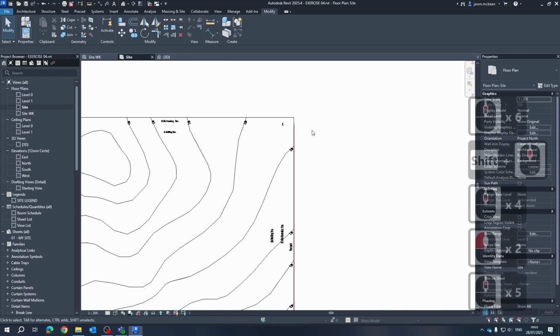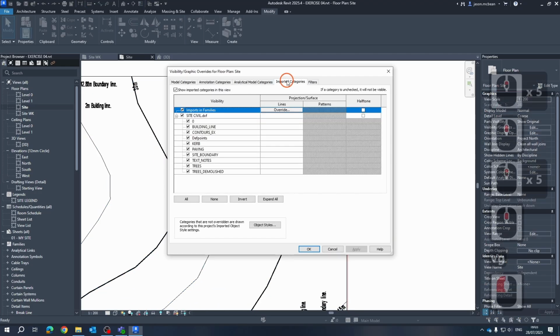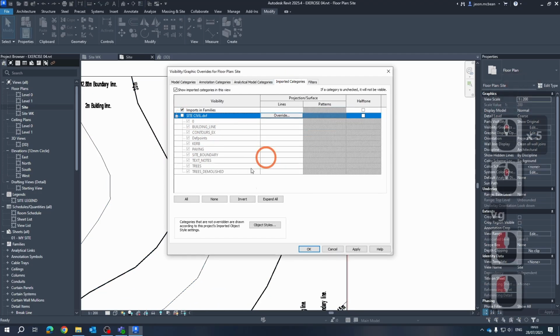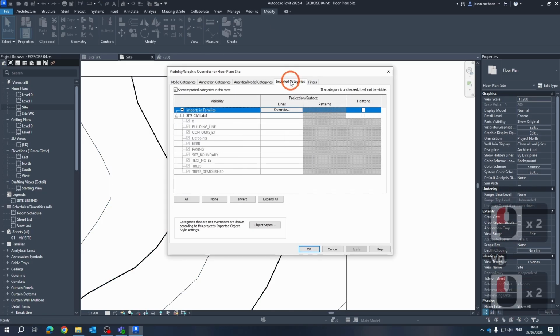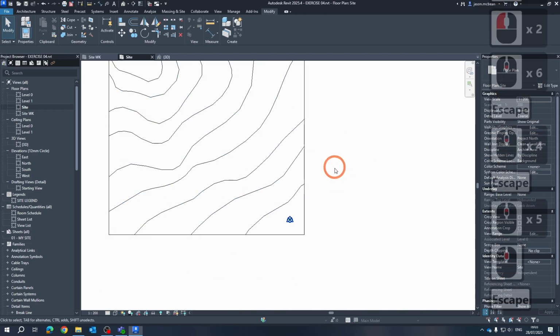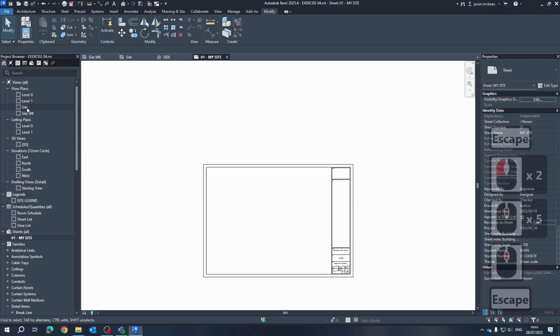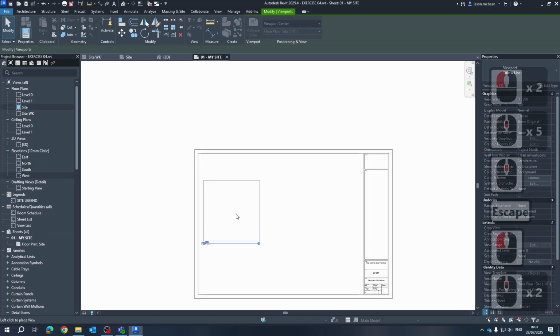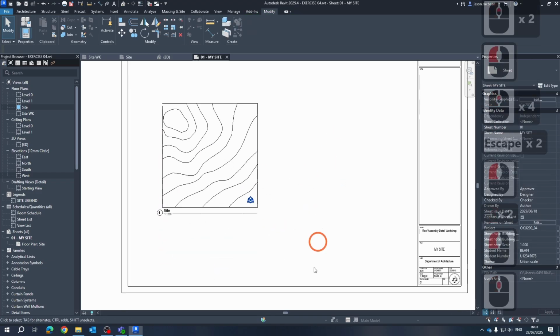In the site view, typically what we'll do now is we'll switch off, so we'll go to VG. Remember, this is going to sit in our sheet, so I switch off the site civil drawing because we've linked this in. So go to import categories, so VG again. Import categories, I've switched the site civil off because technically this is the information that I need to start seeing on my sheet. So if I go to my sheet now, I'm going to drag in the site sheet, because I'm starting to set up my sheet as well.